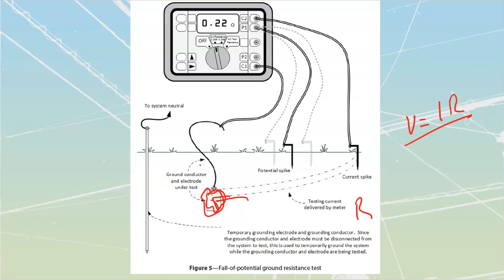If I am going to be doing testing, it's going to be because it's mandated. Places like communications towers mounted on the top of mountains attract a phenomenal amount of lightning strikes, and as a result of those lightning strikes, you can get a lot of equipment damage. It's cellular communications equipment inside of there, so we don't want to see that stuff get arced out. So we want to make sure that there's a relatively good grounding pathway, both for the lightning down conductors as well as for the system ground conductors that are going to be inside of them.